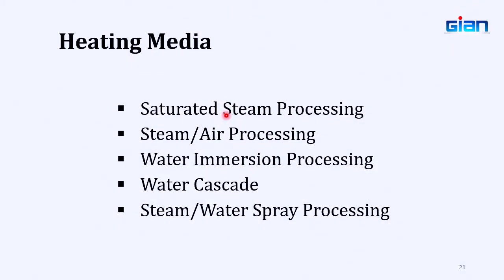So in order to have the additional pressure during cooling, they inject 20-25% air into the steam. So they do the initial heating with the steam and air mixture rather than pure steam. So 75% of the pressure is maintained by steam, and the other 25% overpressure is maintained by the air.